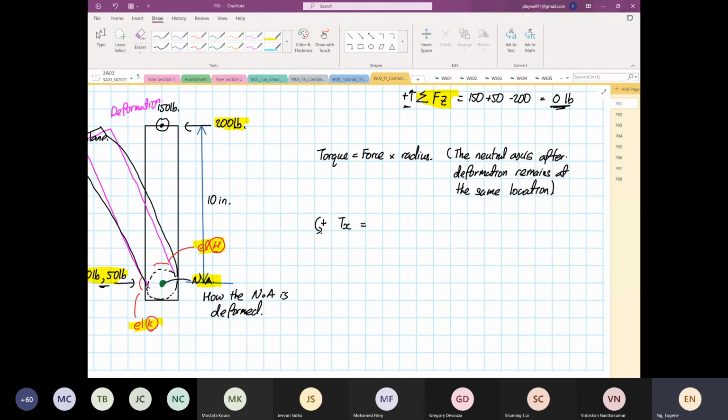But if you put a factor of safety of 10, what does it mean? If you put a safety factor of 10, what does it mean? You have no idea if you're right or not. It means your analysis is not reliable. FOS, right? So you have to have that confidence. I've seen engineers in practice, the value is too small, so they just touch a 1.5. Don't do that. Don't do that.